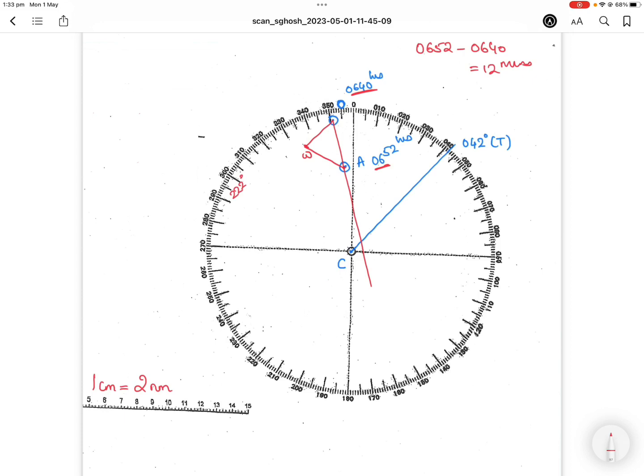Alright, so the first thing that I can plot or measure out is the target vessel's course. So just orient your scale in the direction of WA, going from W to A. So W to A is your target vessel's course. Measure out W to A and then see what course the vessel is doing. I am getting 117 degrees true. So target vessel course in my case is 117 degrees true. You guys let me know how much you are getting.